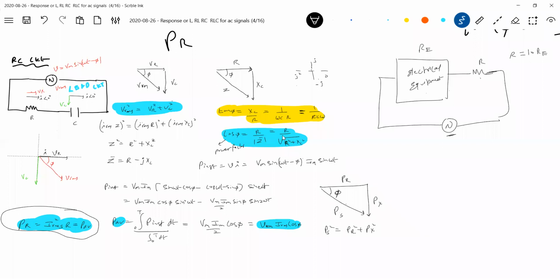than the electrical equipment. And when you make R 10 times RE, if this consumes 100 watt, how much will this consume? This will consume 1000 watt. Means if you get a 100 rupees bill, 90 rupees is due to this and 10 rupees is due to the electrical equipment. This is something very bad, no? And what is the purpose of this? To protect electrical equipment from exceeding voltages. So it is giving protection, but at the cost of consuming 90% of the electricity. If you get a 1000 rupees bill, 100 rupees is what you have actually utilized. The remaining 900 rupees is wasted here as heat. So wastage of power is more here, no?